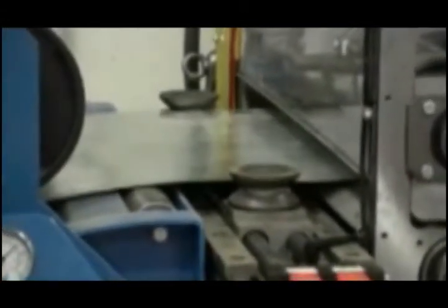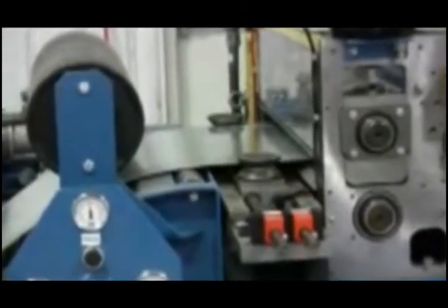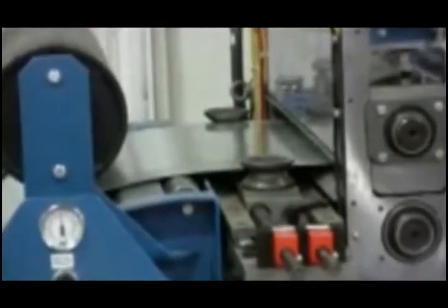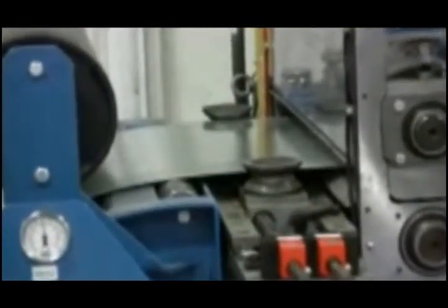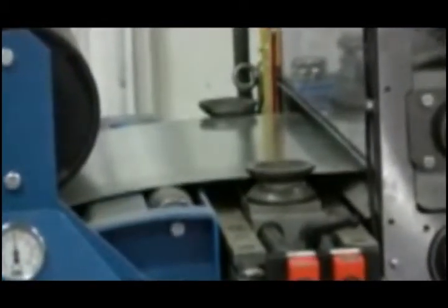So, this video and there are many others. A big rolling mill involves a series of such rolling setups to have a very large deformation. So, you may have a slab of around 7 inch to 8 inch, and it may be reduced to 1 mm or less than that. So, it requires a multi-stage rolling process.